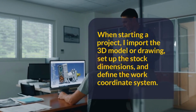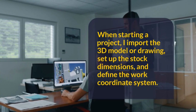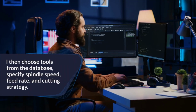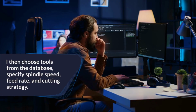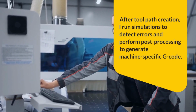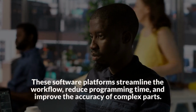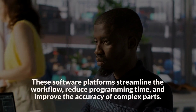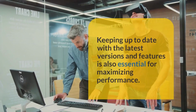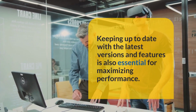When starting a project, I import the 3D model or drawing, set up the stock dimensions, and define the work coordinate system. I then choose tools from the database, specify spindle speed, feed rate, and cutting strategy. After toolpath creation, I run simulations to detect errors and perform post-processing to generate machine-specific G-code. These software platforms streamline the workflow, reduce programming time, and improve the accuracy of complex parts. Keeping up to date with the latest versions and features is also essential for maximizing performance.